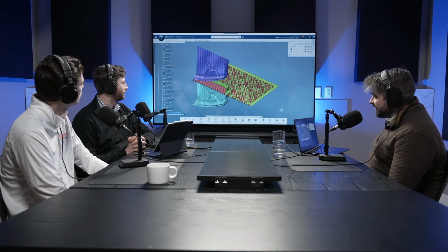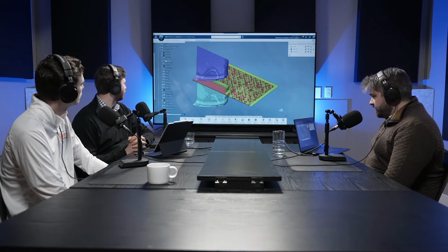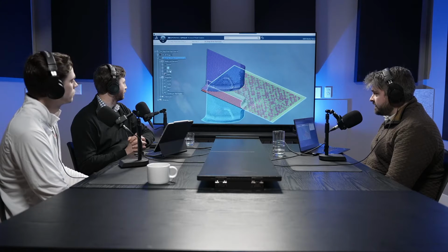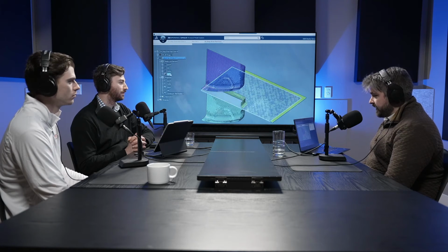So the next thing that we do once we have it uploaded is we have to specify what we're going to use for this role. So we're going to scroll on down to Structural Mechanics Engineer. We're going to go ahead and select that role, and then we need to specify what we want to do within that study. So in this particular case, we're going to create a structural model, right? So we can click that, and we can get to our next step here. And it pumps it in like this. So a couple of things have happened. This actually automatically creates a mesh, and we can kind of understand how everything's set up. Now, I haven't talked about what a mesh is, but just know it's the fundamental building block of a simulation.